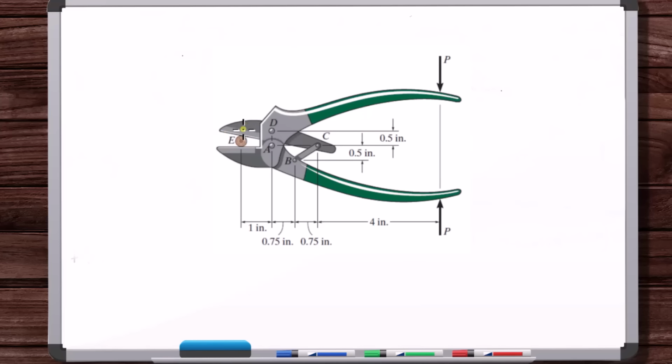We brought this assembly of components, all of these components, as a unit. This is connected, this is connected. These are all rigid connections. The blade here, at least at this snapshot in time, is like a rigid connection, the blade and the twig. We brought this entire assembly of components into empty space. We look for all the exposed surfaces and apply the proper forces there. If it's not exposed, it's an internal force. Now you might be asking, well, look at all of these exposed surfaces. These are all exposed, right?